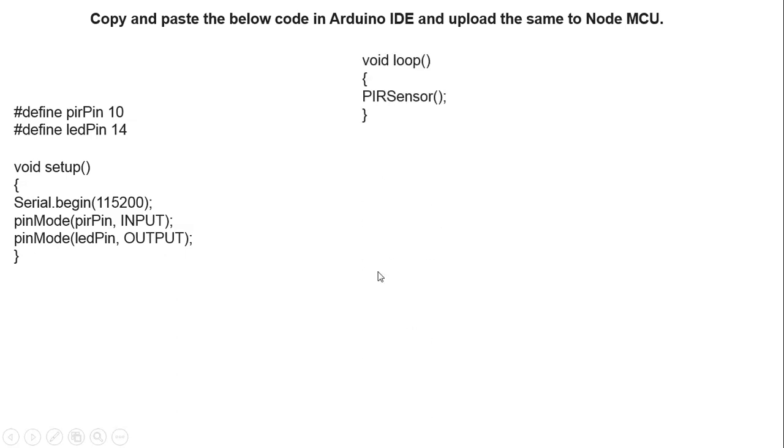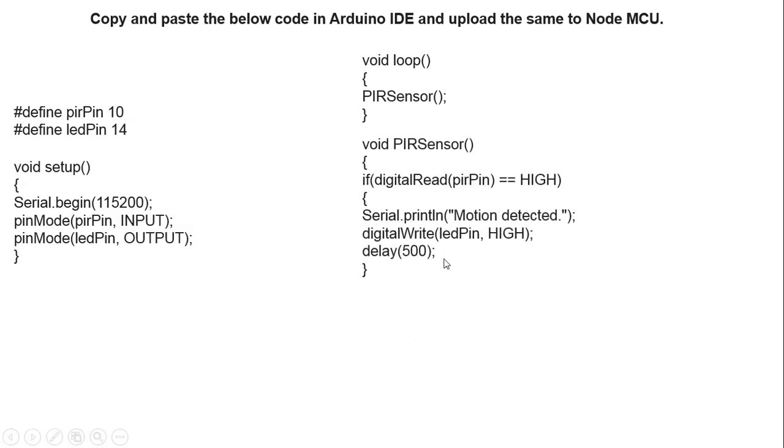So we should be conscious when writing the instruction. Next we have to give that particular task. If the motion is detected, that can be indicated in a void loop. So we create the PIR sensor reading in a void loop. If the digitalRead, why digitalRead? Because the PIR sensor works as an input, so it is indicated as a read.